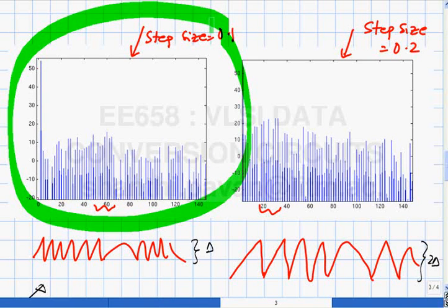You know that the peak signal to quantization noise ratio for an n-bit converter is 6n plus 1.76 dB. So if I know that this corresponds to the full scale sine wave, and if I find the signal to quantization noise ratio from this spectrum, which is easily doable, I should be able to get the signal to quantization noise ratio in dB, from which I can back calculate n.